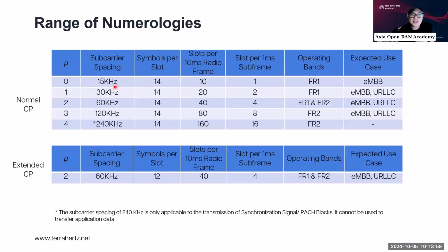So the flexibility was achieved using an OFDM technology where you can adjust yung bandwidth. So that in LTE, you have 1.4, 3, 5, 10, 15, and 20 megahertz. So not anymore fixed sa 200 kilohertz, not anymore fixed sa 5 megahertz.